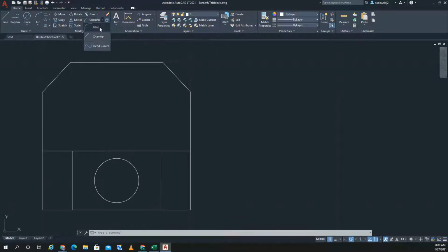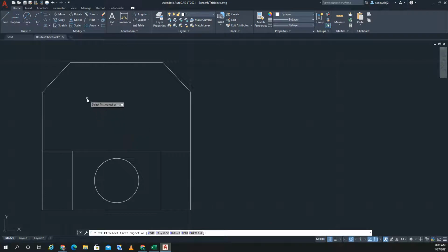Acts just like the fillet. Remember, it's under the fillet command. It's in the same family. All right, we got to this little slot in here now. So using midpoint, and that thing is about 0.5 now. And 0.5 across, so since we're cutting in half, 0.25. And trim all this up.